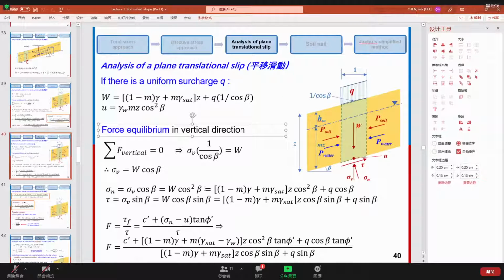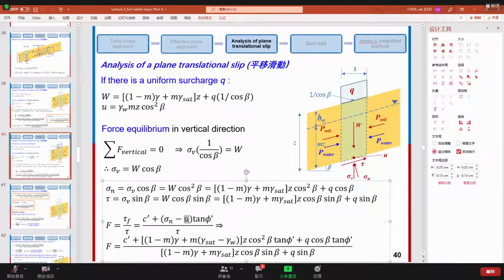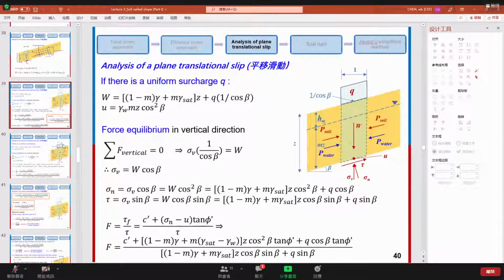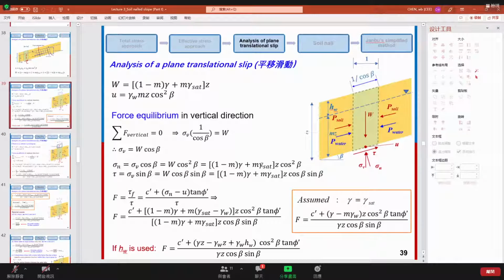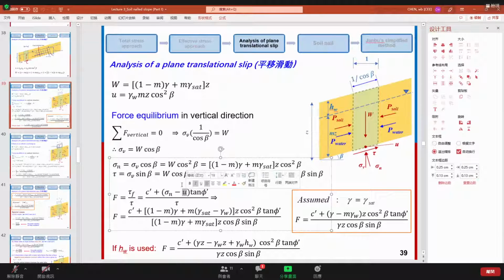The meaning of the effective stress approach is that we need to consider the effect of the pore water pressure, and deduct the pressure due to the pore water pressure. So in slide 39, even though we use gamma saturate, when we really calculate tau f, we still use sigma v prime: total minus the pore water pressure is equal to sigma v prime.